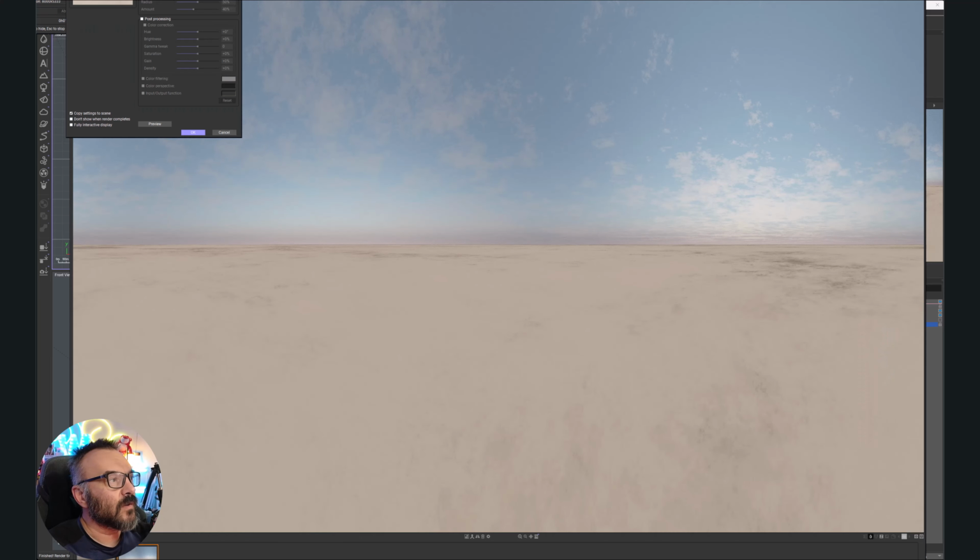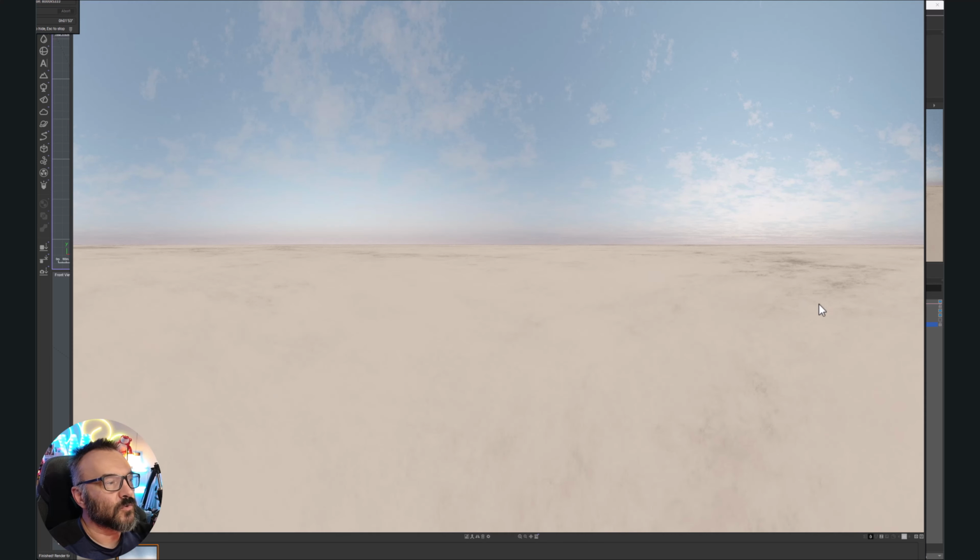Okay, so the render is completed. Let's see, after exposure off. I don't like after exposure. There's our scenery. We did render 360, so we rendered everything. You don't necessarily need it if you want just the sky. You can go with 160 on the upper dome render if you need it.